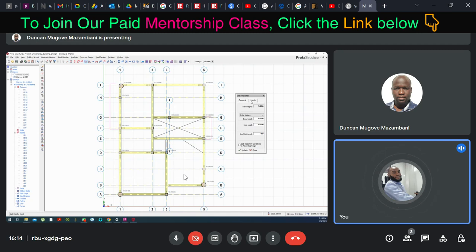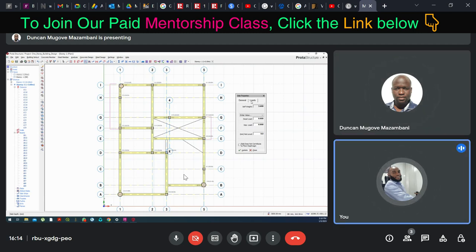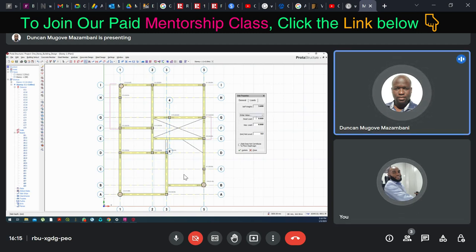Finishing load should be 1.0, then partition should be 0.5, which makes it 1.5 as your dead load.